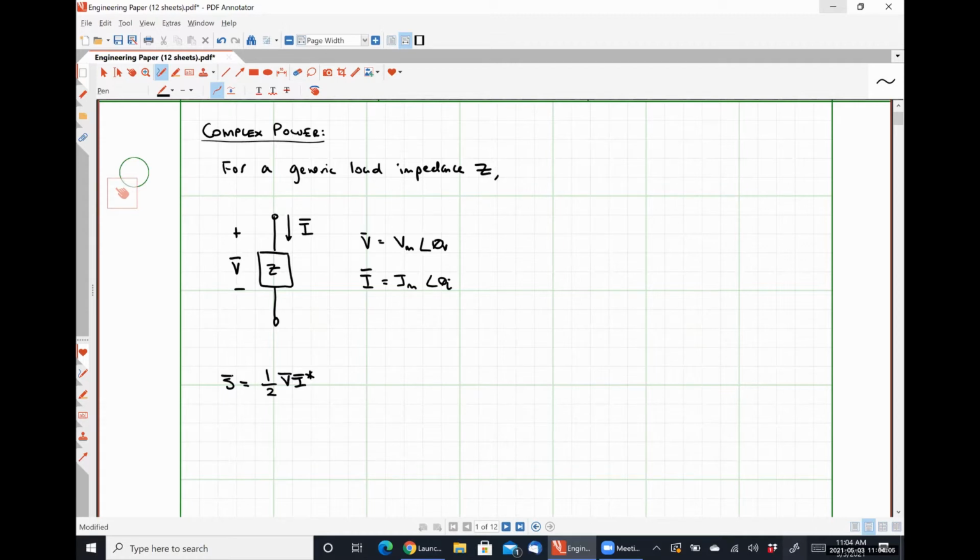Now, carrying around this extra factor of 1/2 can get pretty annoying pretty quickly, okay? So instead, we are going to be working in a new domain. I'm going to call this our frequency domain relationships. And we are now going to be working in what I'm going to call the RMS phasor domain. All right, so to denote that we are in the RMS phasor domain, I choose to, instead of putting a bar over everything, put a little squiggly hat on top of it, letting me know that this is representing a sinusoidal quantity that is an RMS value.